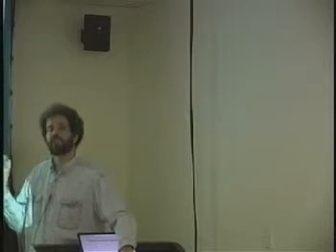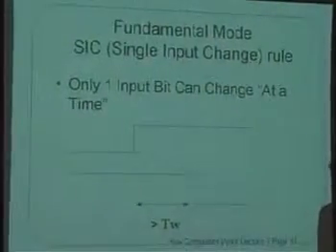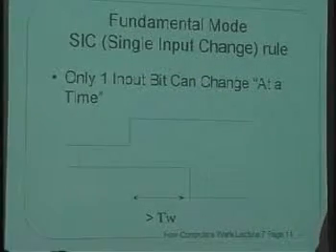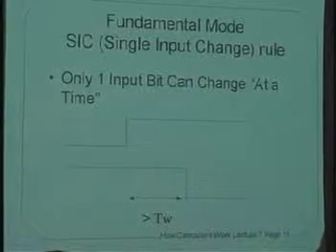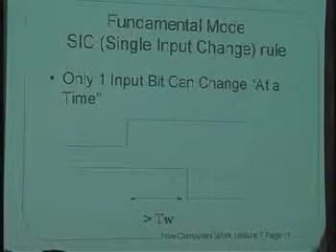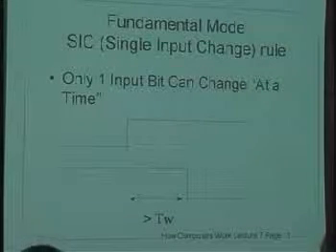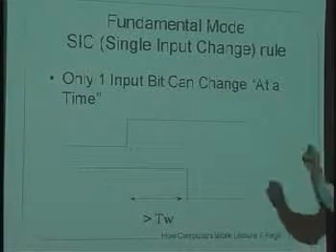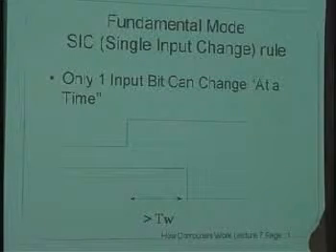And the reason I'm going to talk about the exception is that we're going to use it to build a flip-flop. It turns out that the exception is an extremely restrictive one. We're only going to guarantee that an output of a logic circuit is hazard-free under a very specific condition: that only one of the inputs is going to change at a time. In other words, if the output was supposed to be high, and only one of however many inputs there are changes from 0 to 1 or from 1 to 0, that change can take as long as you'd like, but only one at a time.